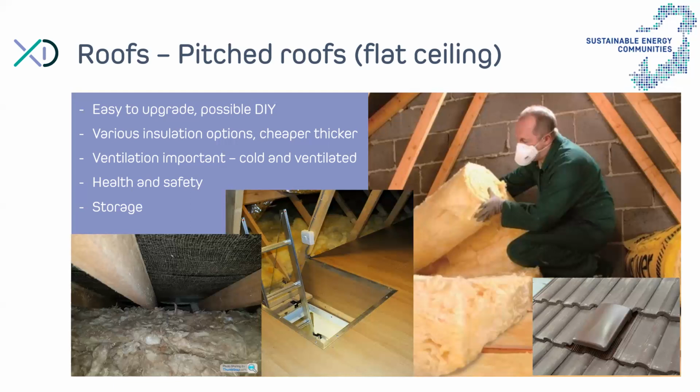In many cases, it can be a DIY job. So you can go to the hardware store and install that insulation yourself. Obviously, you need to be careful, health and safety first. Put on a mask, as the fibers of mineral wool insulation can be an irritant as well. So there are a few precautions to take.